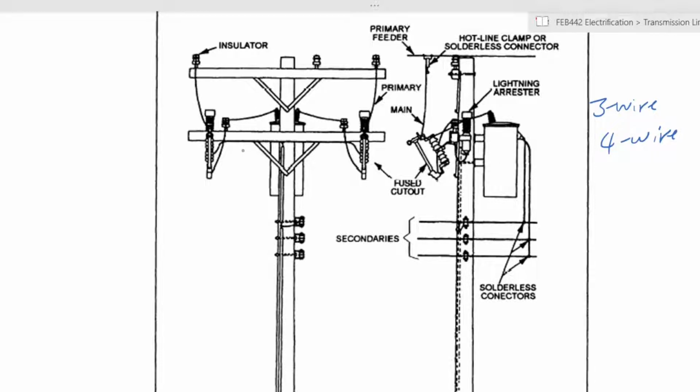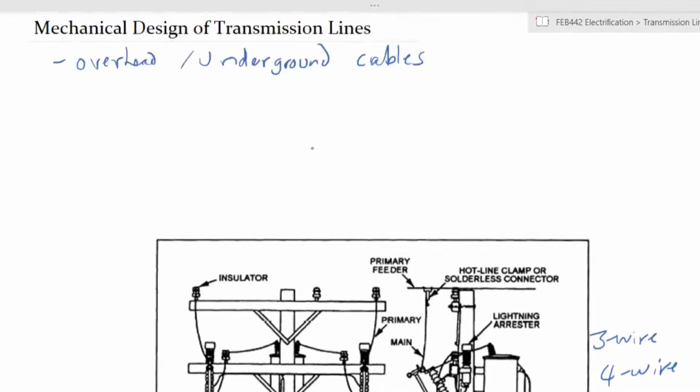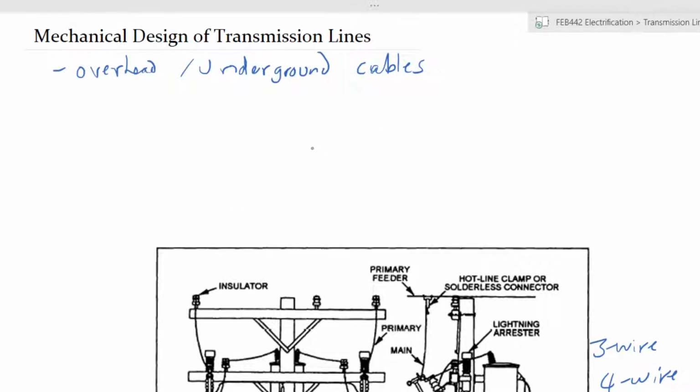So in this particular diagram, you have a pole mounted electrical distribution system, or transmission lines that are pole mounted. Now, in the case of overhead lines, you will generally have bare wires, and that is one of the main advantages of overhead wires, that in most cases, the wires will be insulated by the air itself. They'll be insulated from each other by the property of air not to conduct electricity. And that is sufficient for you to transmit your power in a system that is overhead.